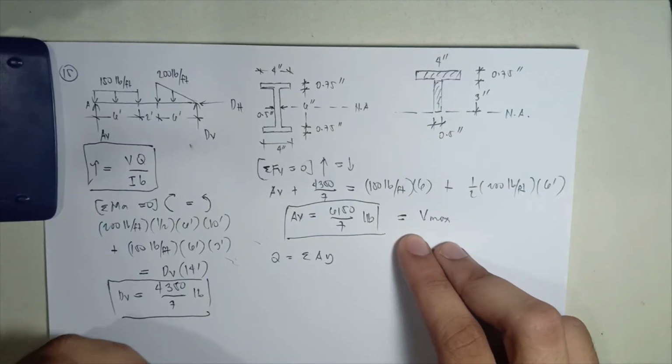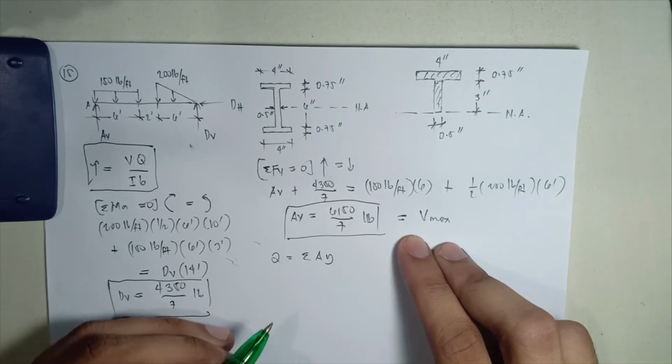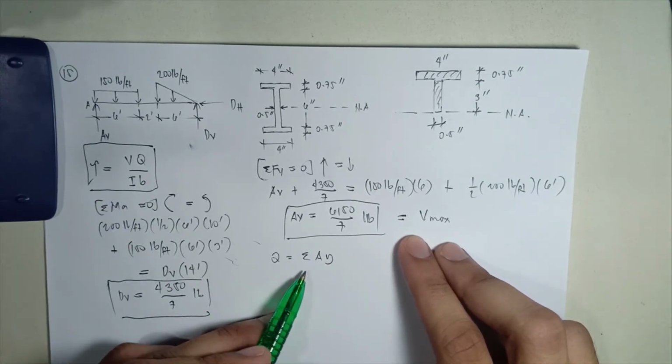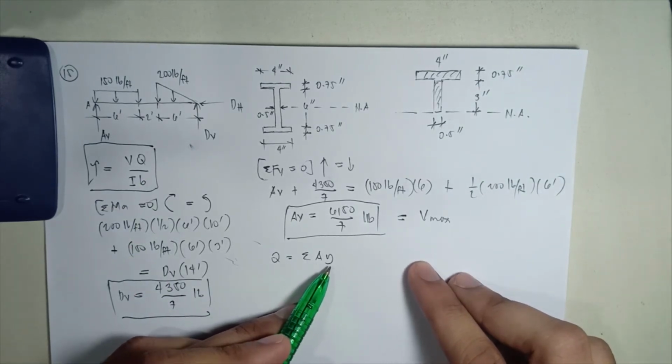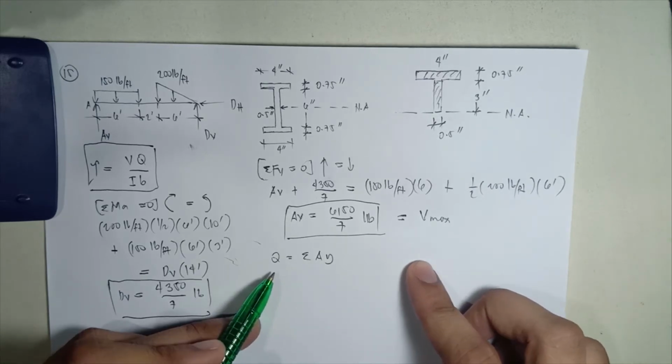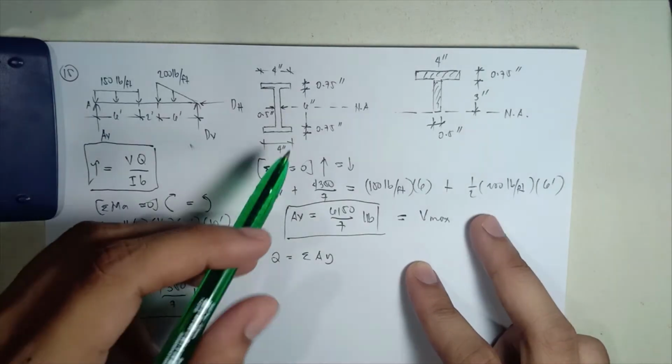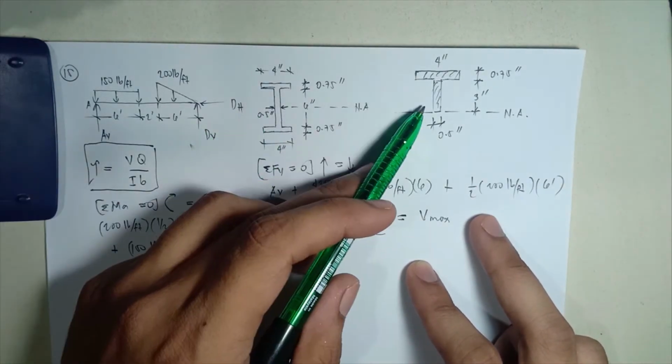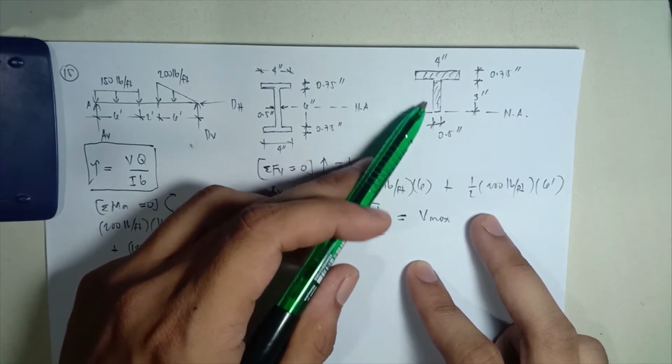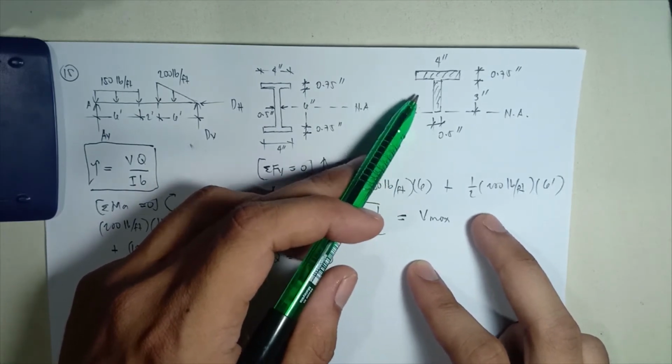Ngayon, i-solve naman natin yung first moment of an area or letter Q, equivalent yan sa summation of area times Y, or Y is the moment arm of the area. And Q is the first moment of an area above or below the neutral axis. So, since symmetrical yung area, pwedeng gamitin natin yung area above the neutral axis. So, let's say this is the area na i-consider ko.